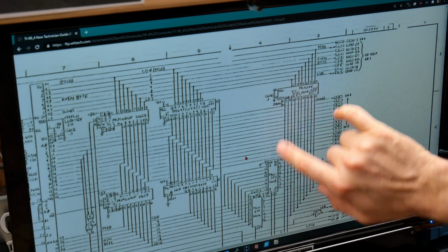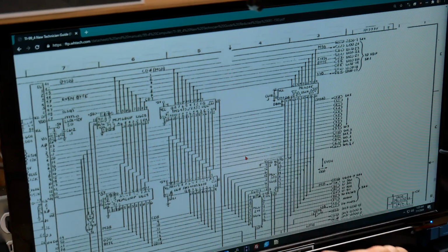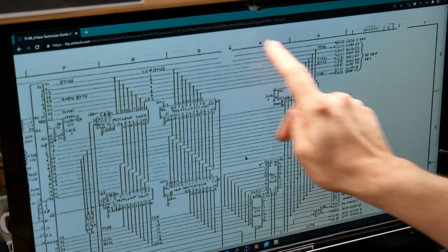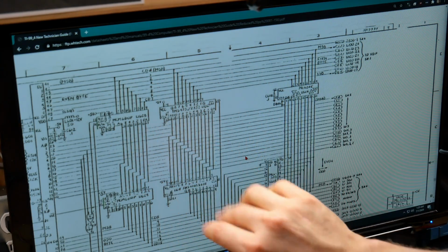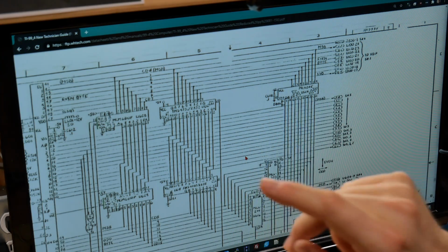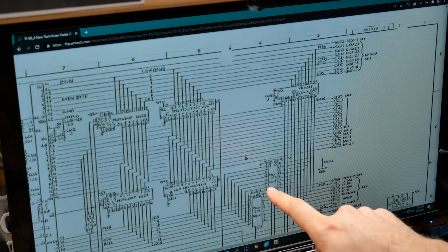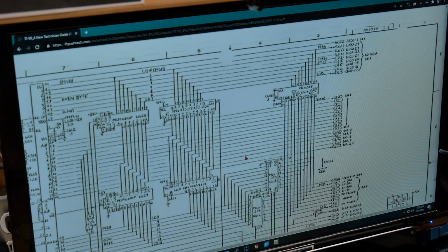And then these 3 ICs and these 4, the 2 ROMs and the 2 RAMs. So there's a fault in one or more of these chips on this data bus that is causing this computer not to run. And I am pretty sure that if I figure out which one of these is bad and I fix it, well, that should make this computer work.